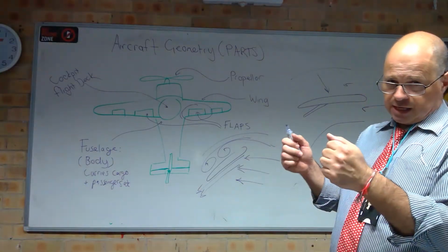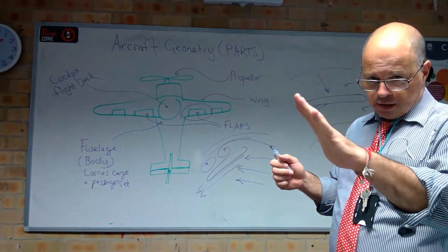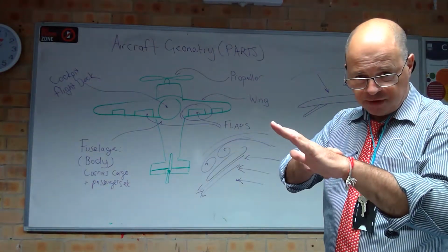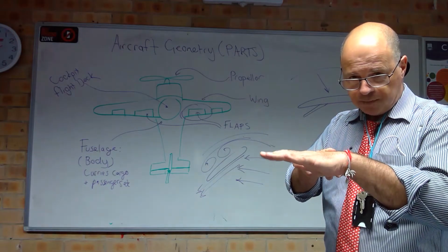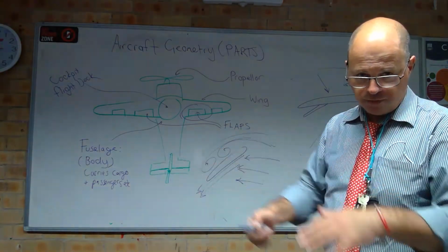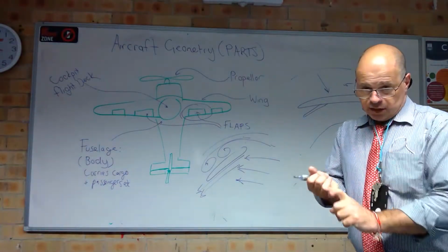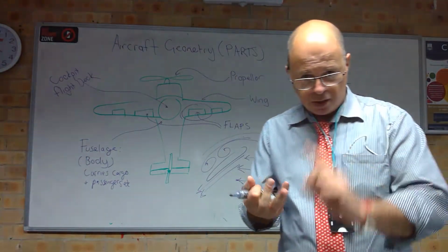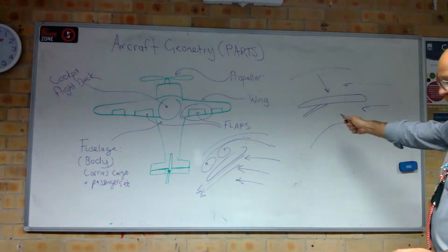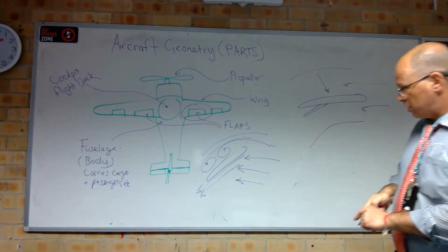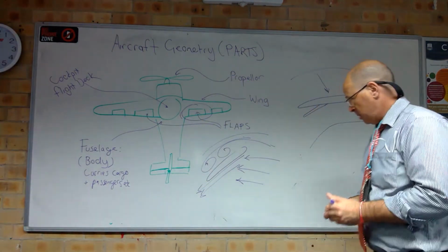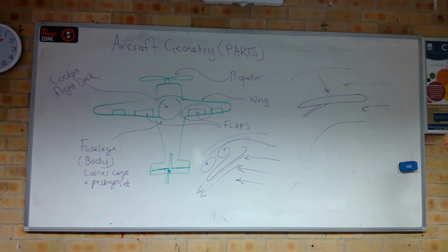So if you wanted to maintain lift and you're coming into land, the aircraft is going to have a high nose attitude. You can't see the runway properly. So you throw out flap, which means you can travel slower at less of an angle of attack, okay? Which means the runway is more visible. So that's another reason. Increasing lift at slow speeds and lowering the nose attitude for approach and landing, okay? That's how your flap works, okay? So you would throw out both of these flaps on approach to land, and so that's a flap for you.